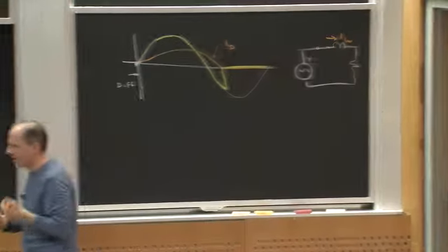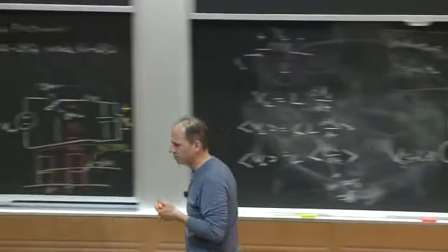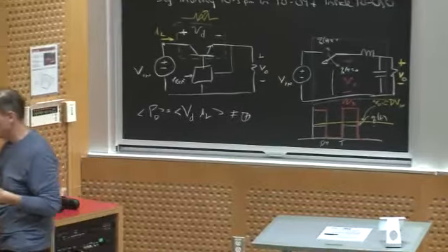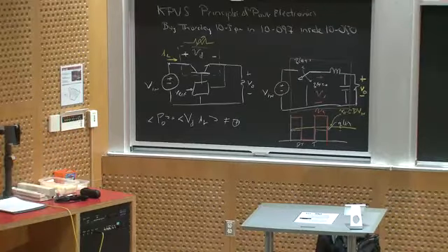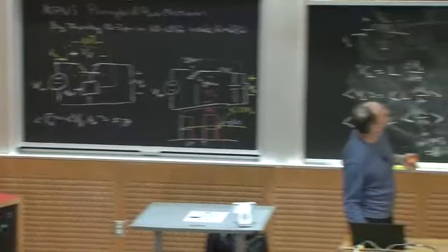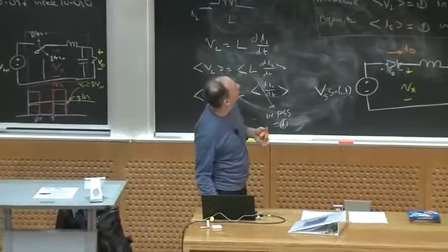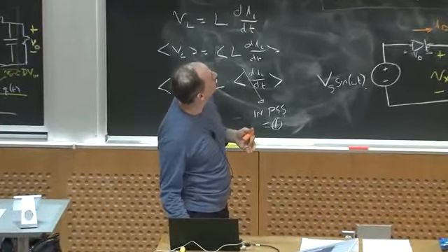Just to illustrate that, I've got a simulation here to show you. And all I did was go into LTspice, which I encourage you to all download, and simulate it. So here we have a sinusoidal voltage source, an almost ideal diode. We gave it a small forward drop, but if we gave it a 0 forward drop, it would be ideal. We put in a big inductor and a resistor.